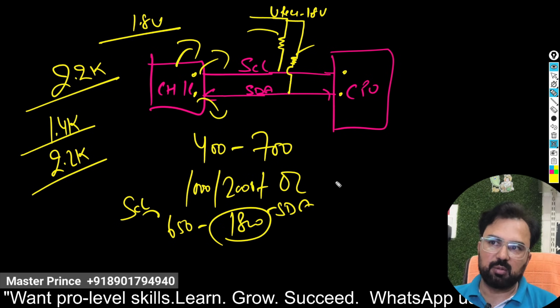If both lines have a problem, then you must reball first. Open the CPU, first check the communication, whether both lines are connected or not, right? If they are connected, then you have to reball the CPU and your phone will turn on and work properly.